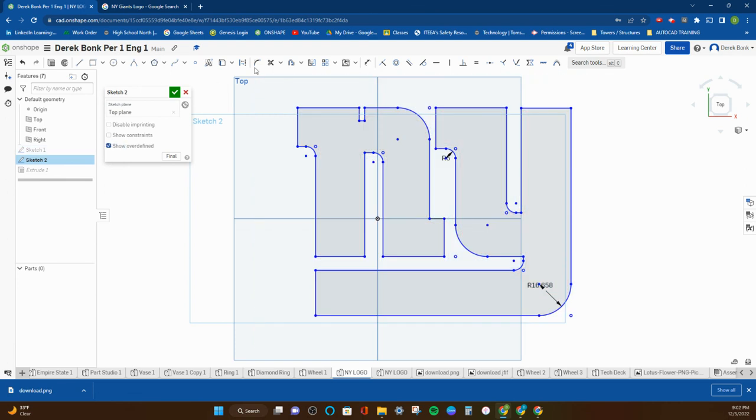So if I turn this off and I look up, there's an offset tool for situations just like this. You can click them one at a time. You could also drag and select things. In this case, I need just the end. In some cases, you can't get to everything without selecting things you don't want to select, so you might have to go back in here and add to your selection to get this right.